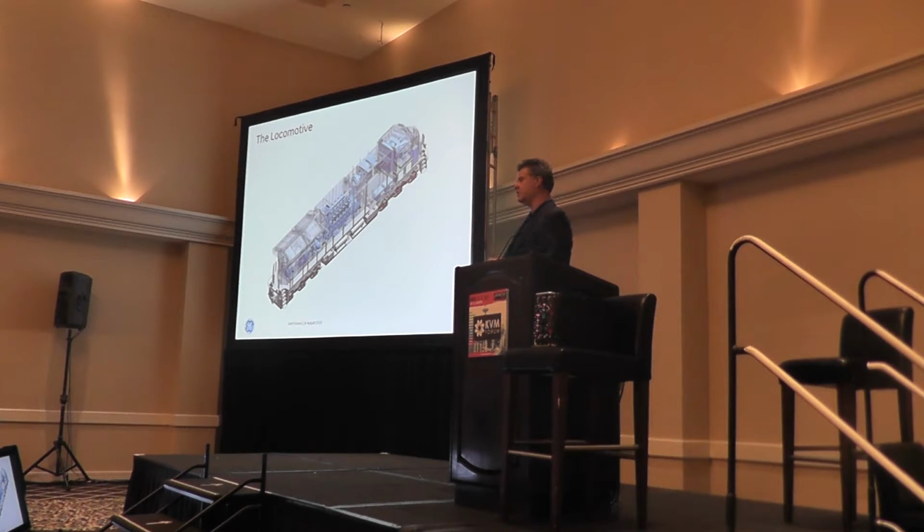So weight's not a big concern. For us, really, power's not a big concern, right? We've got a power plant on wheels, so whether I use 10 watts or 8 watts, it really doesn't make any difference. For us, in our electronics design, the most important thing is heat, heat, and heat, which does kind of translate to power. All of our electronics need to operate from minus 40 to plus 70. The middle of Australia gets really, really hot, and northern Canada gets really, really cold. So we need to survive basically all those different temperature extremes.